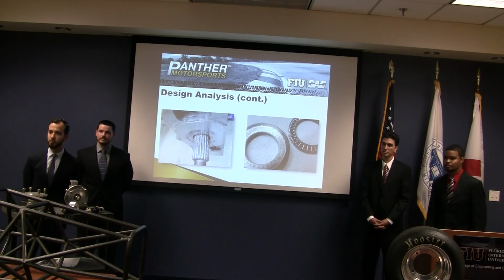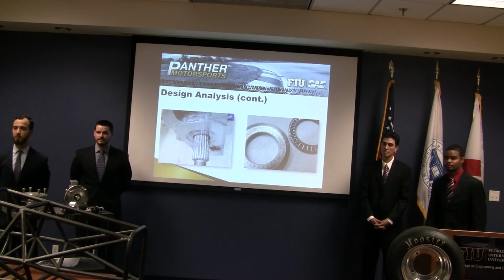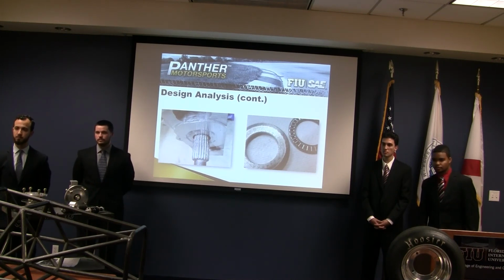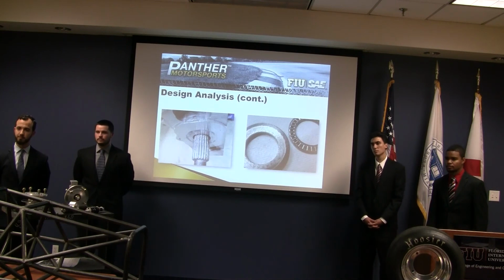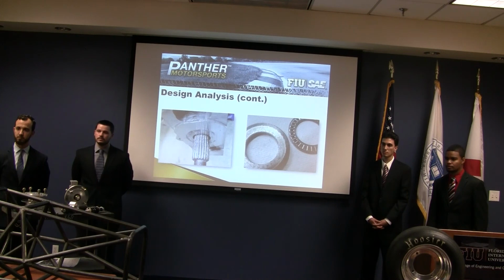Okay. Do you have, yeah, please. We're running short, related to the welding, and I'll make it very quick. You've done SolidWorks, you've done some analysis, so you know what's going on with the stress and strain in the frame elements and all of that. So if that is all good from your analysis, the joints are going to be where the weak link is. I heard the question about welding that you will do later on to ensure there's integrity in the welding as well as in the frame. I didn't see where you spoke about any kind of NDT or other destructive testing to verify that integrity. Could you speak about that real quick?